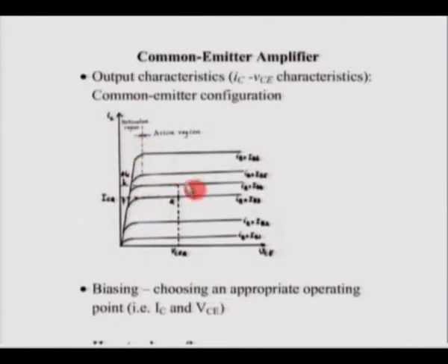So, we should choose an operating point somewhere in the middle. Also, we should ensure that the transistor never goes into cutoff, which is towards the x axis. So, you would choose somewhere in the middle.